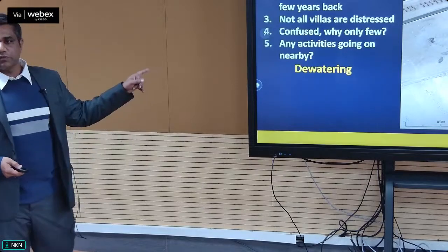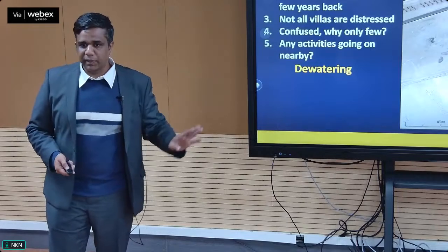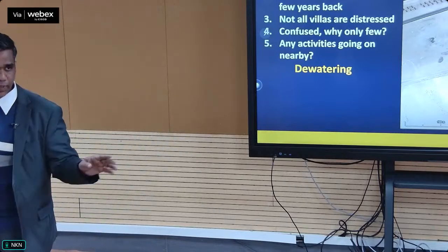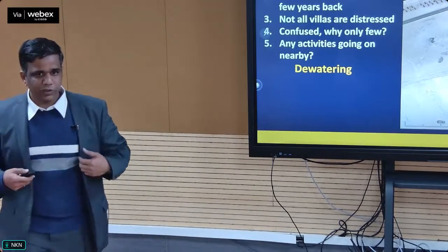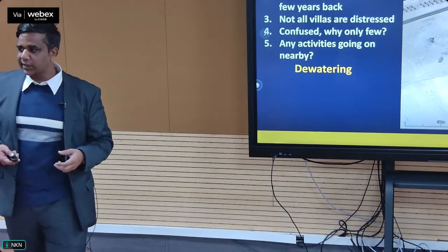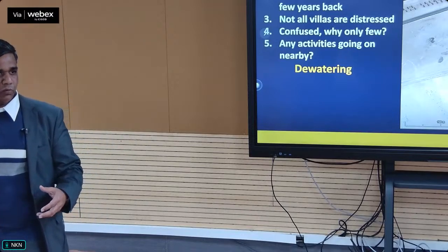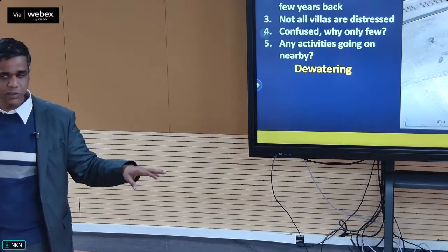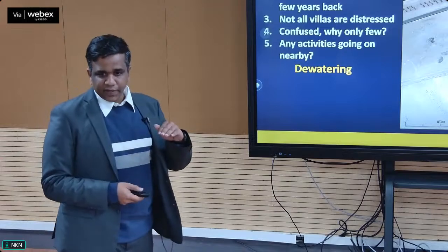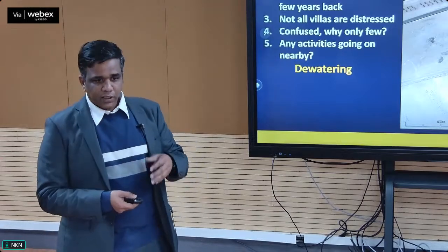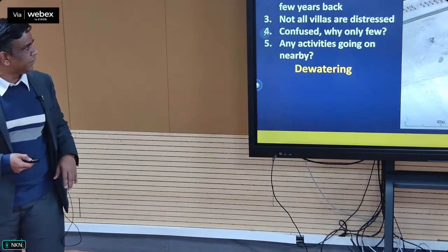The reason for this particular project is that we had dewatering at that site. For example, those who know swimming feel light when swimming in the water, and when they come out, they feel heavy. Similarly, whenever we lower the water table in the ground, the material which feels light in the water becomes heavy. Understand? Because of that, the weight of the soil increases and it collapses the soil below it. That is one of the problems we faced.